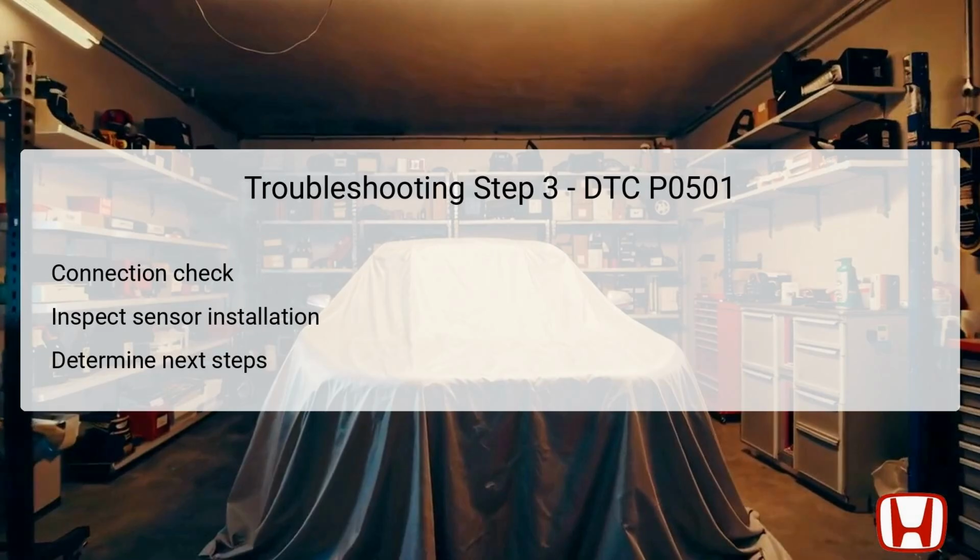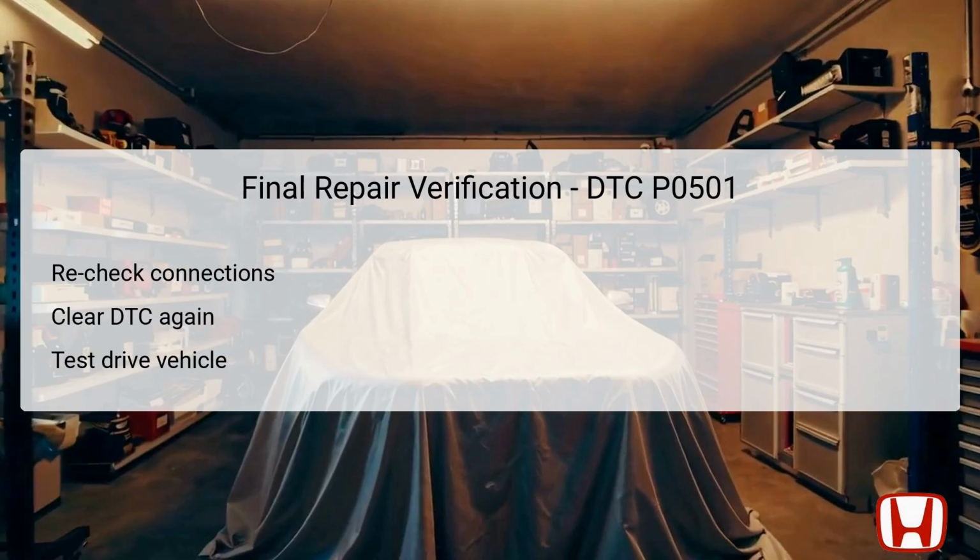If all connections appear secure and installation is correct, the next course of action would be to replace the CVT speed sensor, as it may be malfunctioning. If the connection is found to be poor, repair it to ensure a reliable circuit. After completing repairs, it's essential to conduct a final verification to ensure the issue has been addressed.